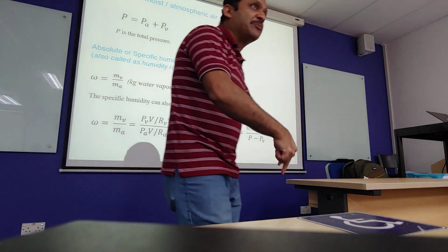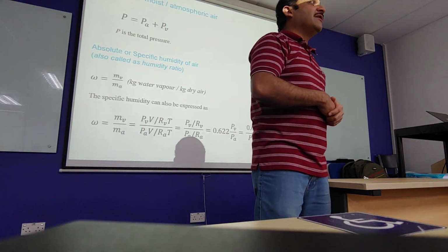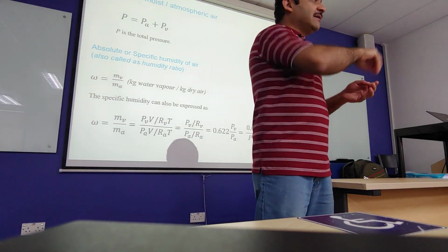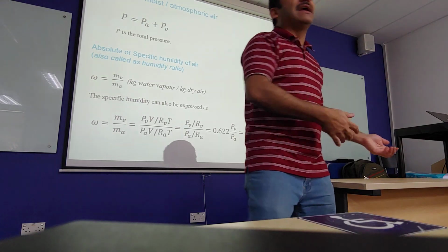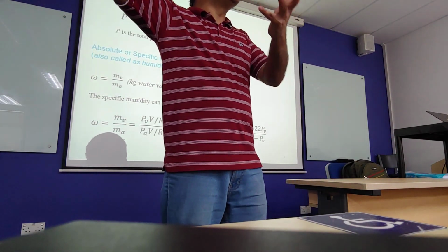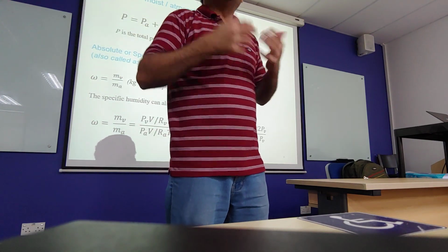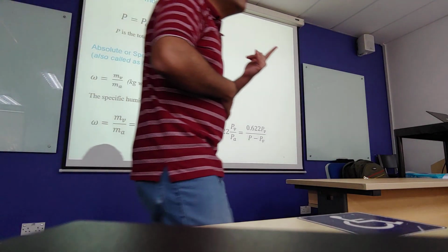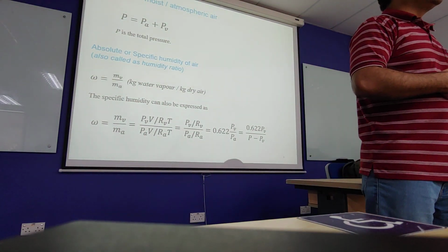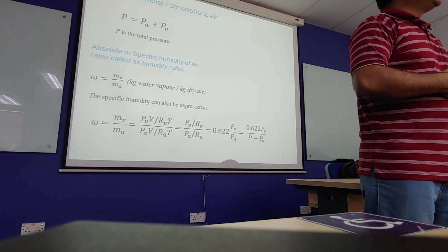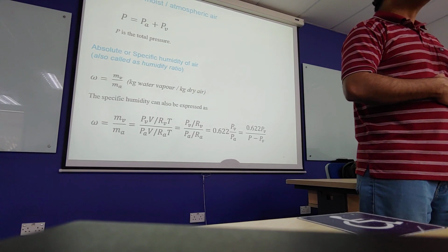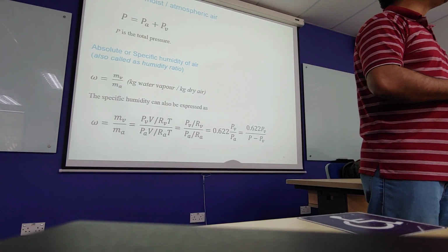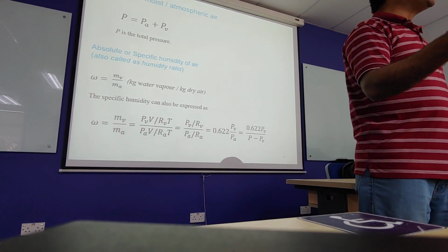Now, how much lower a temperature can it read? If you keep pouring more and more water at room temperature on top of that tip, can it read negative 40 degrees Celsius or negative 50 degrees Celsius? What's the lowest temperature do you think it can read? Just the temperature of the water? It can read a temperature lower than the temperature of the water, a few degrees, and that will be the wet bulb temperature. And that's how evaporative cooling systems work.